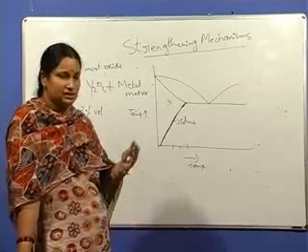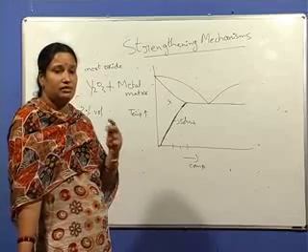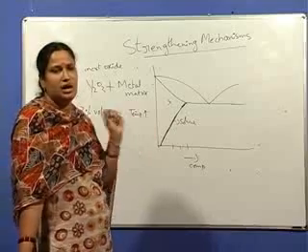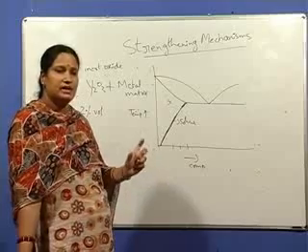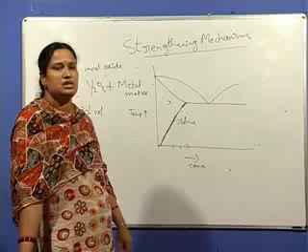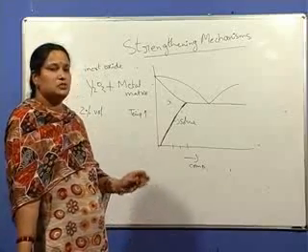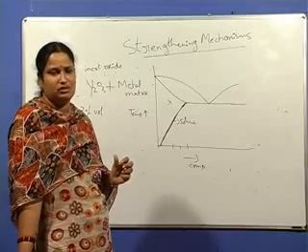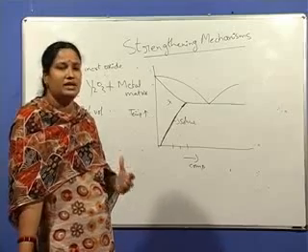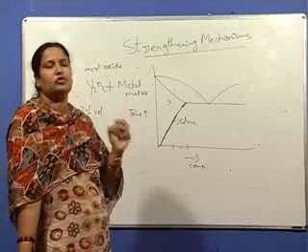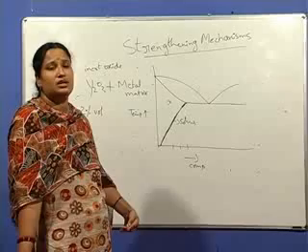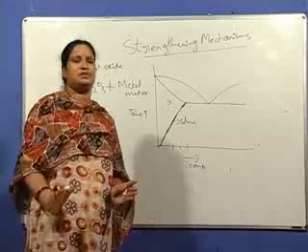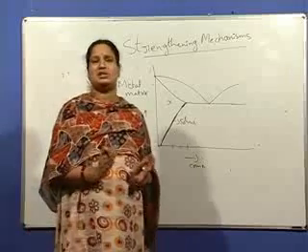And moreover, when compared in terms of strength, the precipitation hardening mechanism contributes to a greater strength when compared to the dispersion strengthening mechanism. But the one advantage of dispersion strengthening is that even at higher temperatures, the dispersoids do not coarsen, they do not react with the matrix, they are not soluble in the matrix, and they undergo very little coarsening. Whereas the precipitates undergo coarsening at very high temperatures, thereby the strength drops down. So this is the main difference between dispersion strengthening and precipitation strengthening.